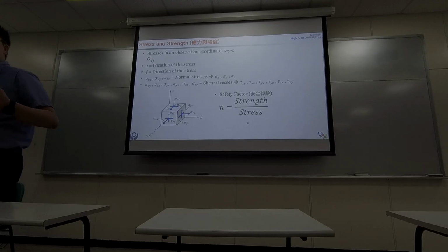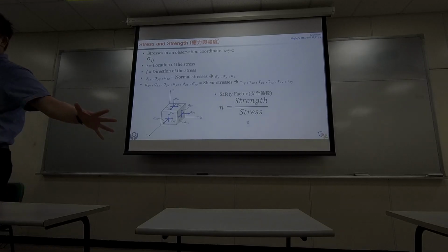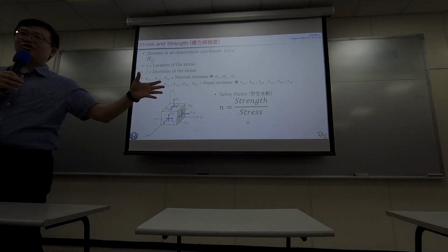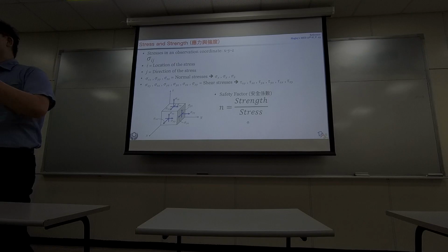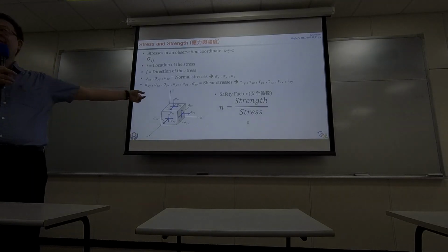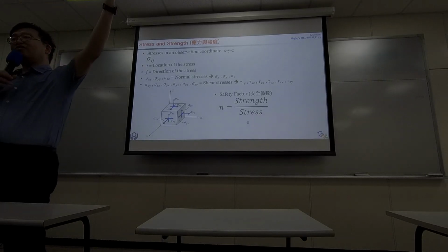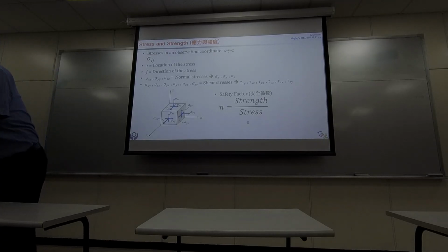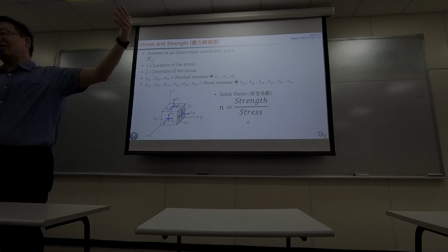If I have this kind of dynamic or fluctuating force applied to anything, there is a different kind of failure, the so-called fatigue. So for everything, there are two different ways of failure. One is just breakage. The other one is fatigue. In the first part of the lecture, we talk about static load and how a part could fail. In the second part, we talk about dynamic loads. We will give you some models for design against fatigue.